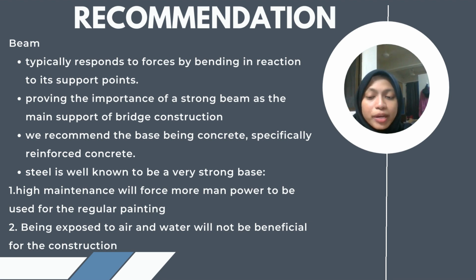There are three types of material that we use for beams, which are steel, concrete, and wood. In this case, due to the location that we chose, the bridge is a railway bridge. So we recommend that concrete be used for the base of this bridge, specifically reinforced concrete.